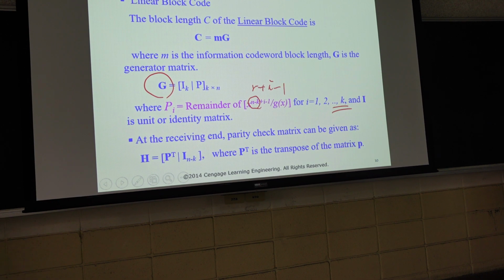We also draw your attention to another calculation, called this matrix, the matrix used to find the syndrome. We have this H. If you want the direct calculation, this is the way: you need to transpose the current matrix P and combine it with the identity matrix I of n minus k, I_r, so that you have the parity check matrix.